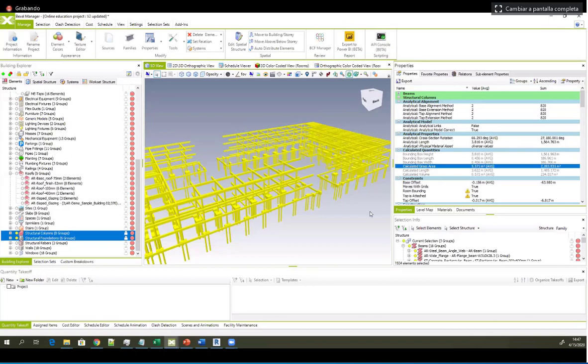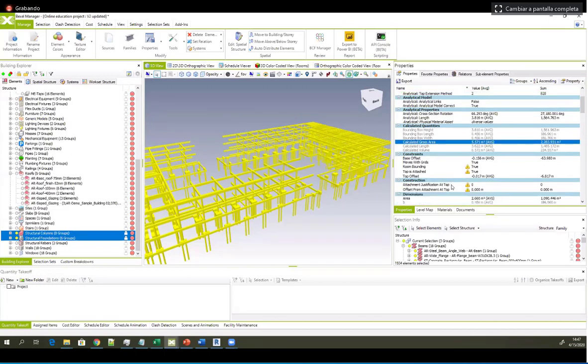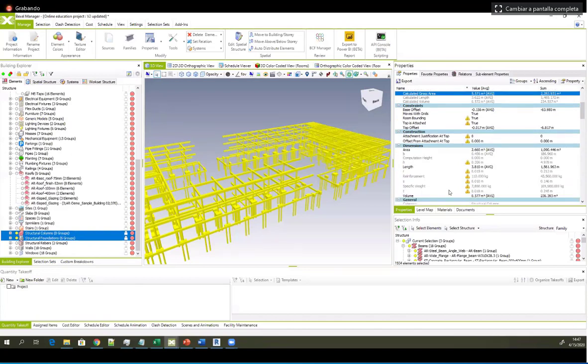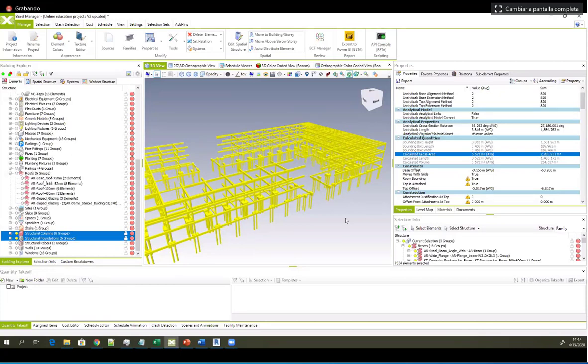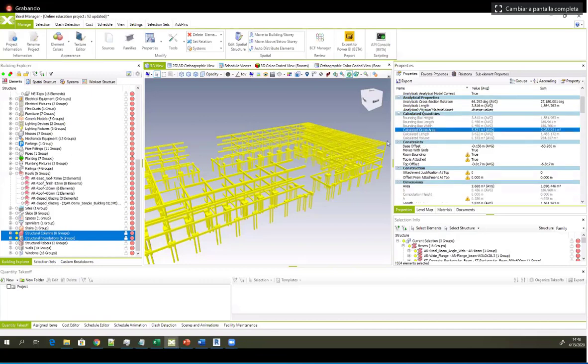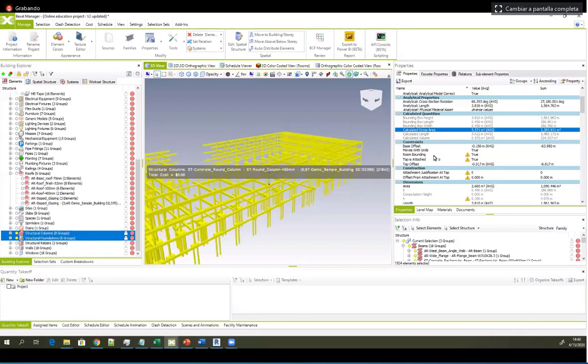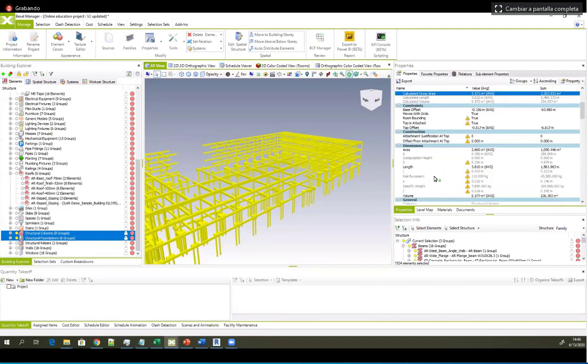And this is something that can help you, but we always recommend that you use the values coming from the authoring tools. But sometimes, if you're using some mass model or some generic BIM model elements which don't have accurate information, and your authoring tool does not provide the quantities, you can use calculated quantities, which Bexel Manager provides for you. But again, I have to repeat, this is something Bexel Manager calculates from the geometry of the model, and it should be used if available information from the authoring tool does not exist.